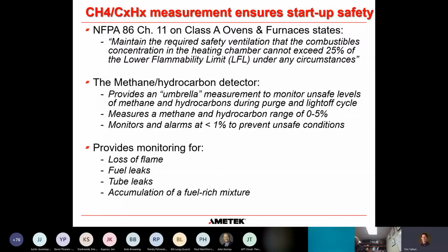It operates within a 0 to 5% range, so that you can alarm at less than 1% of the LFL, or less than 1% of methane in the heater, to prevent unsafe conditions. Now, when we designed the hydrocarbons and methane detector, it was originally to serve this need within NFPA 86, Chapter 11, to make sure that the heater is always below 25% of the lower flammability limit. That's really where it began, as the perception for startup conditions.